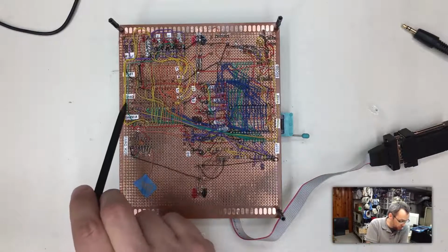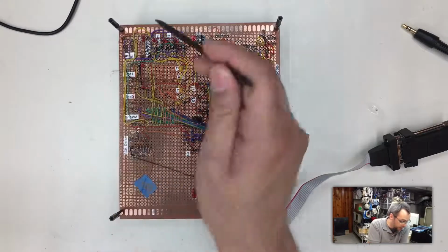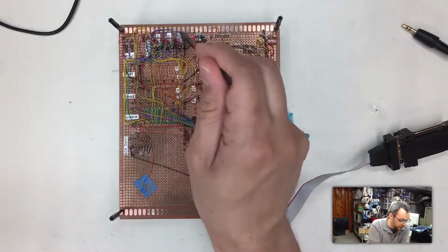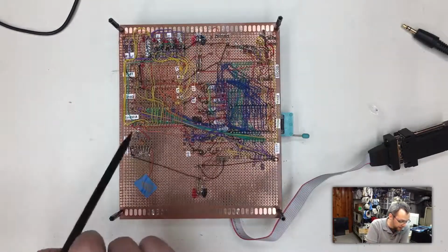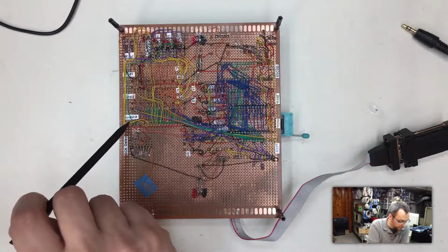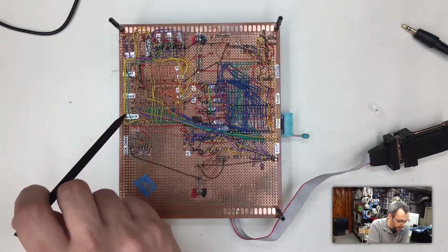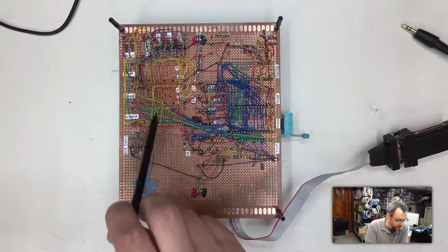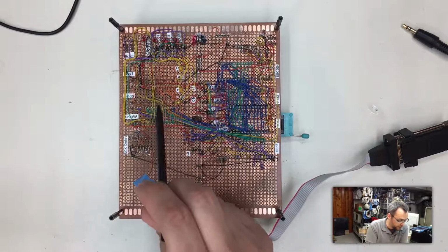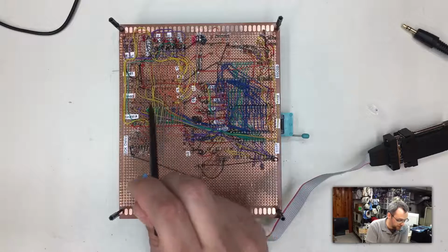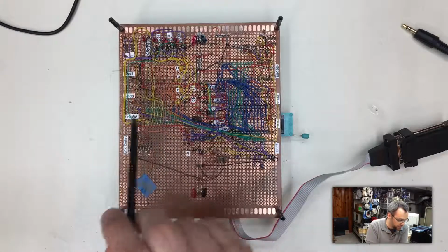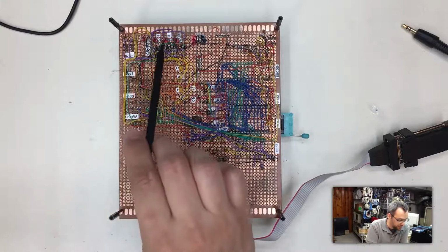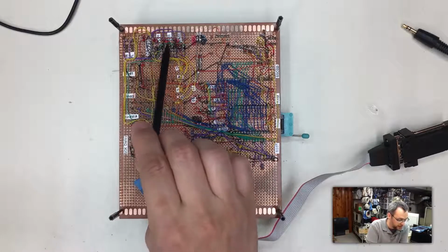These yellow wires right here, you can see we've got them coming up into the inverter, and they come out of purple lines and go into each of these. These are extra parallel output ports, the PB ports, some of which I'm using, as I showed before, to select the different chip selects for the audio chips, but these right here I'm using as my chip selects for these guys here.